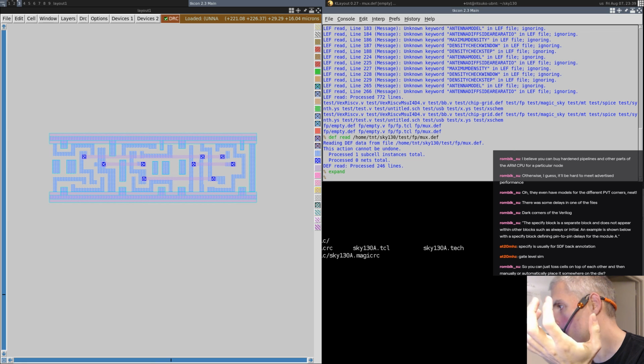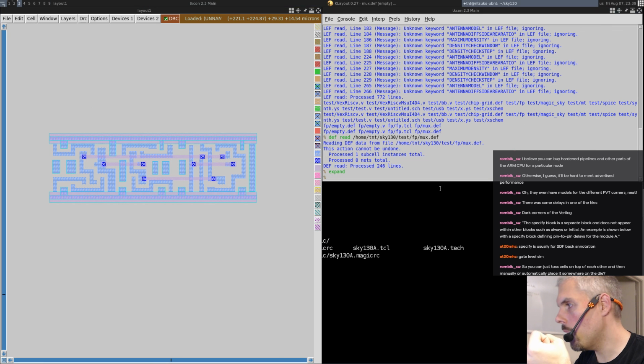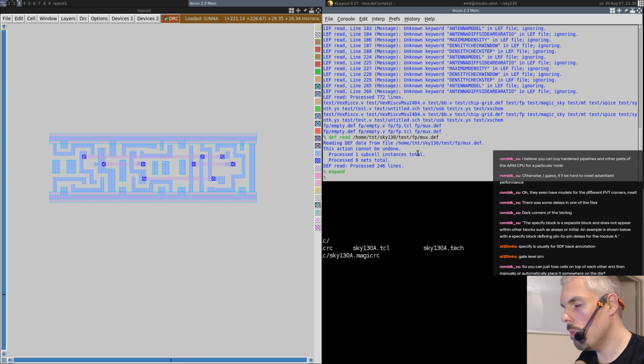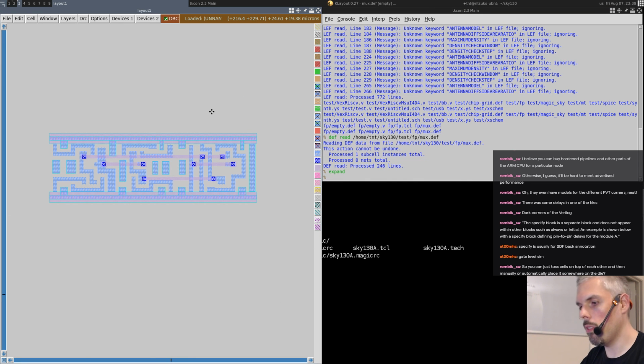that's what the automatic placer does, right? And it even does that in two steps. If you look at the floor plan DEF of the first design we looked at, the SPM design, all the cells are actually placed at 0, 0. And the first step of the placer is to distribute them among the die, or the area that you defined as the area you want being used for your cells.